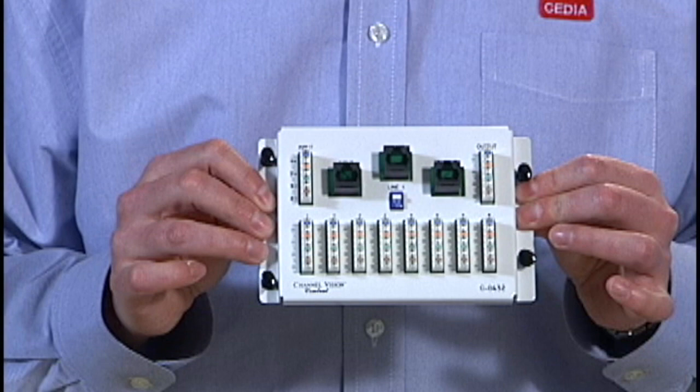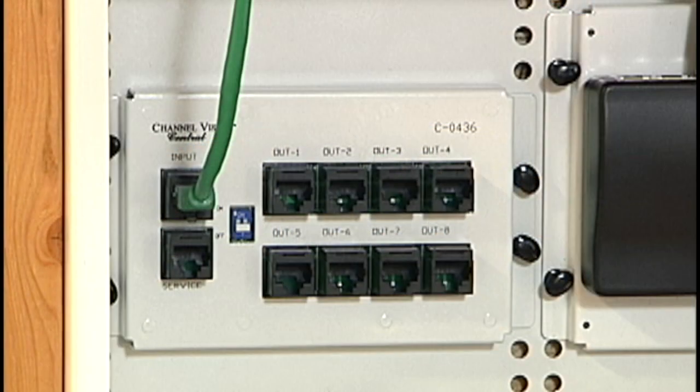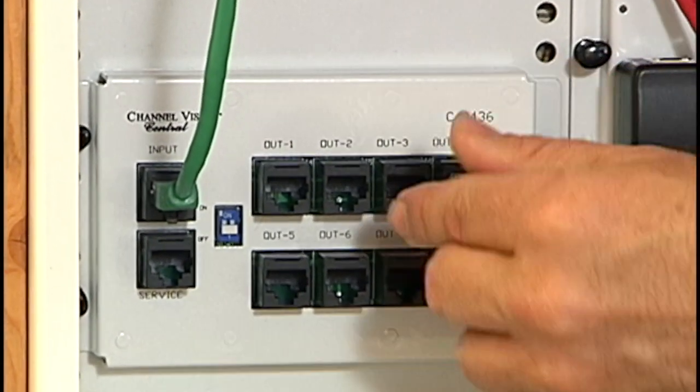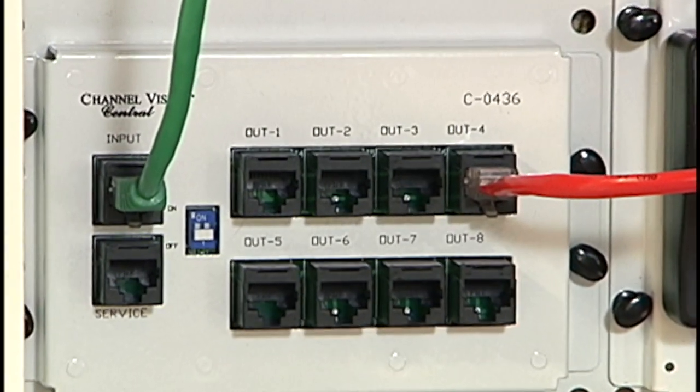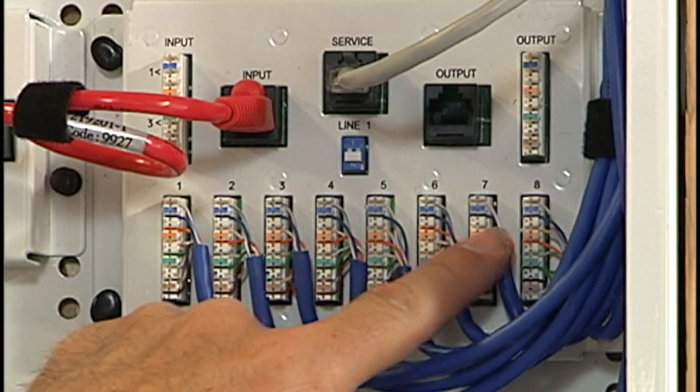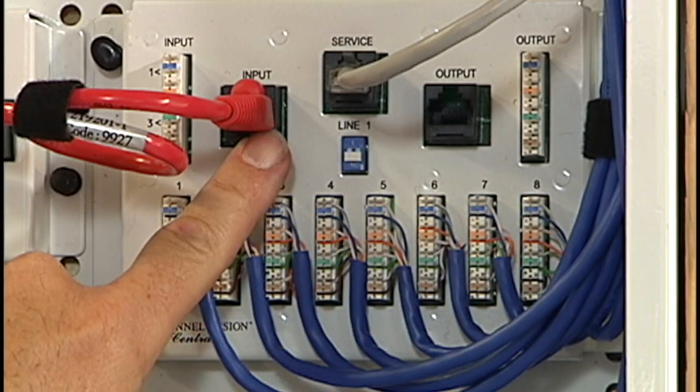Each manufacturer of structured cabling products will have some type of voice network distribution module with or without a cross-connect. There are 2 methods used to terminate the TP cable runs to the module. The first terminates the cables in modular connectors. The cables then plug into the voice distribution module like this. The other method terminates each cable in a 110 style insulation displacement connector. The connectors are wired in parallel and connected to the incoming voice lines.